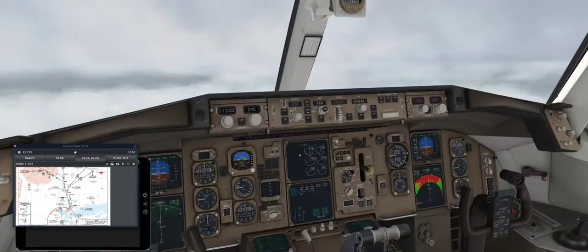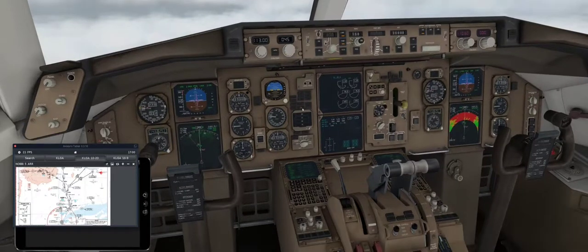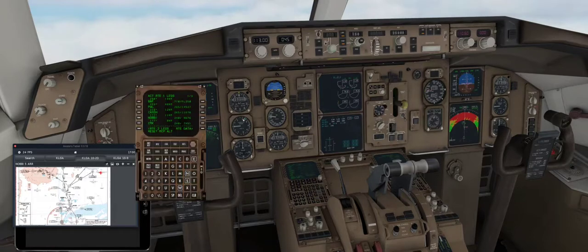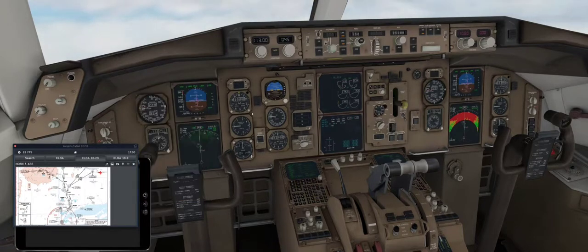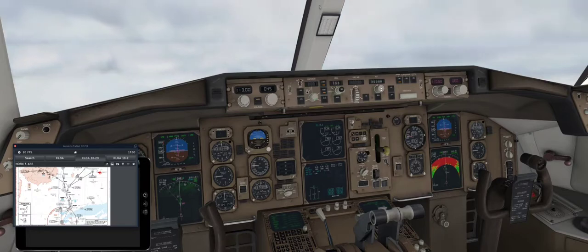And we'll get a warning. Oh, FMC. See how this popped up? It's the FMC needs our attention for something. Reset MCP altitude. I said we were going to talk about that, and then I totally forgot. It knows we're getting close to the top of descent, and I have not yet given it permission to descend.